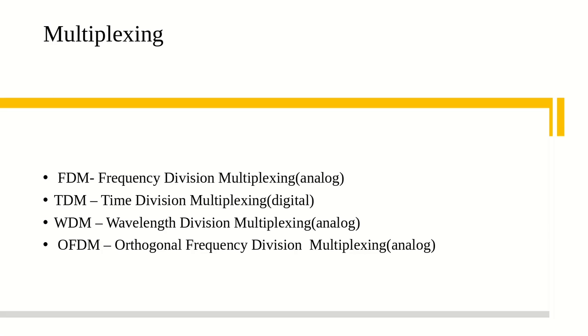Bandwidth utilization is about achieving some goals while using the available bandwidth. The efficiency can come from multiplexing, which means sharing bandwidth with multiple users. We have wavelength division multiplexing, an analog multiplexing technique for combining optical signals. Time division multiplexing is a technique for combining several low rate digital channels into one high rate one. OFDM, orthogonal frequency division multiplexing, is a form of multi-carrier modulation, which consists of a number of closely spaced modulated carriers.